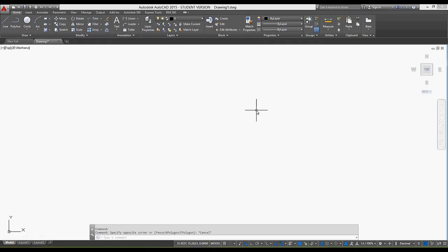So if you don't know what a command is, you can essentially look through that list and guess what it is. Now, the structure of AutoCAD, and you'll find that with AutoCAD there are many different ways of doing something. The structure of AutoCAD to allow us to enter the command can be done in essentially 3 different ways. The first way is by clicking the toolbar button. The second is by entering a command, and the third is by using what's called an alias.